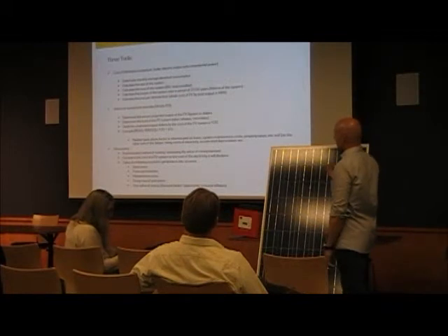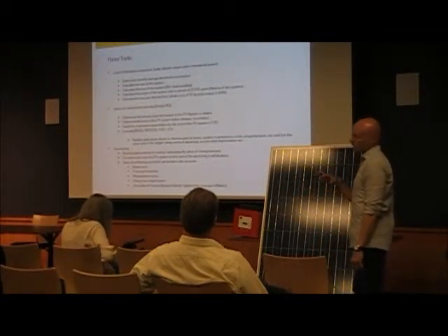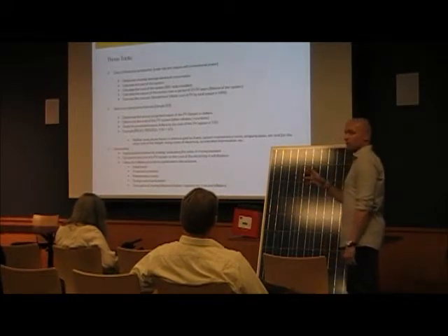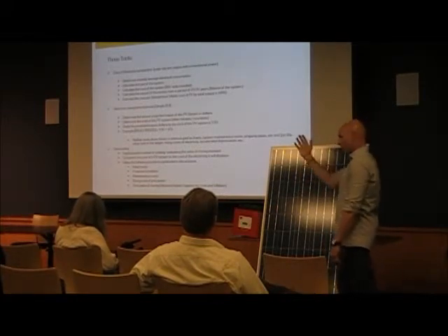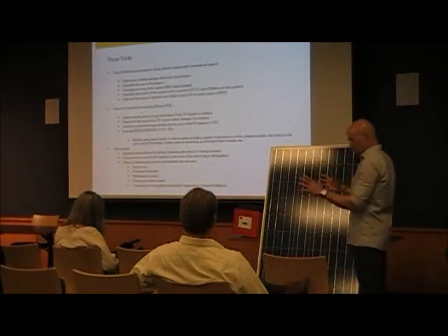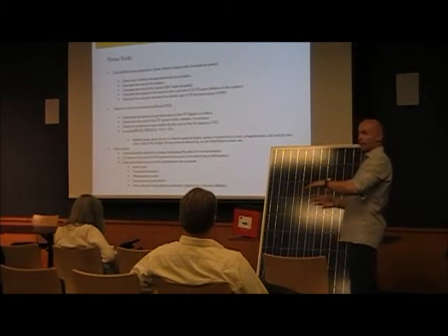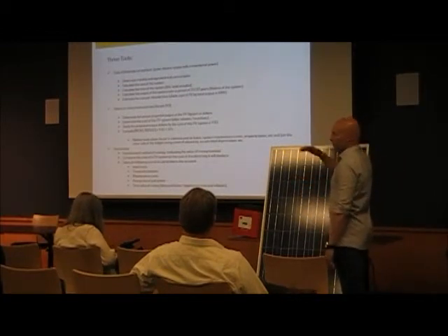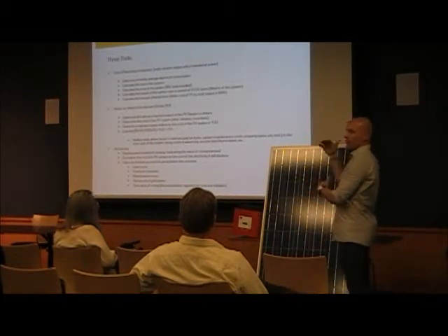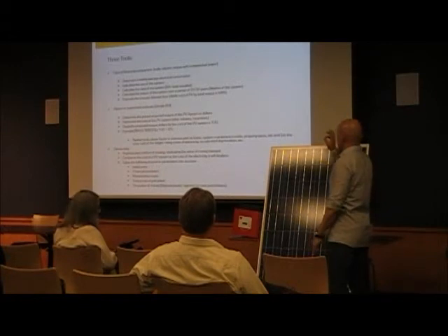In Alliance territory, when you apply for PV, they come out and do an audit. It costs about $100 as a homeowner, $250 as a commercial owner. They'll audit your location and give you certain options to lower your demand, and then they'll give you certain incentive levels. They have a standard level and they have an efficiency level. If you do the efficiency measures, they're going to give you more dollars per kilowatt hour in your first year production. I'll show you what that is.